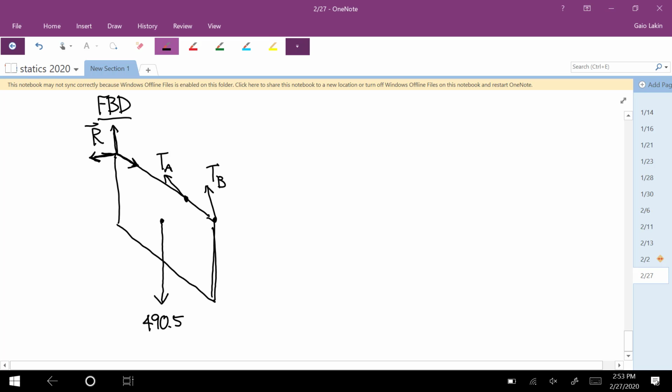Okay, how many equations are Newton's laws going to give us? 6 total, yep. And how many variables do we have? 5 in this case. This is something that's going to be pretty common in 3 dimensions that we really never see in 2-dimensional problems: pretty often, not all of the 6 equations are going to be useful. What we're most likely going to see is that one of our 6 equations, when you write it out, just ends up being 0 equals 0. So we're going to have only 5 useful equations to solve for 5 variables. Okay.